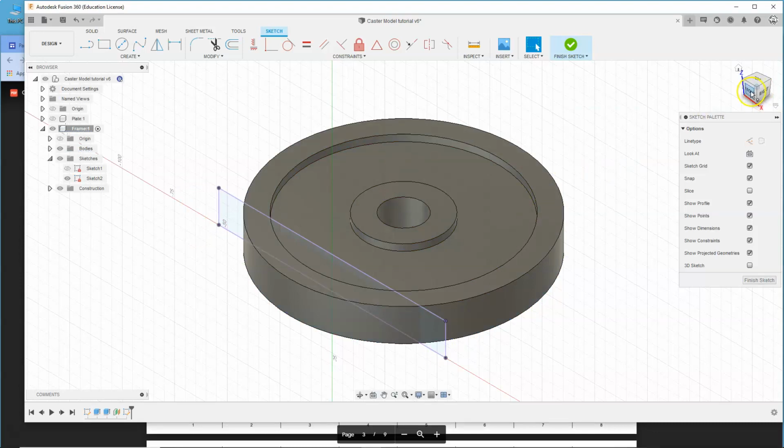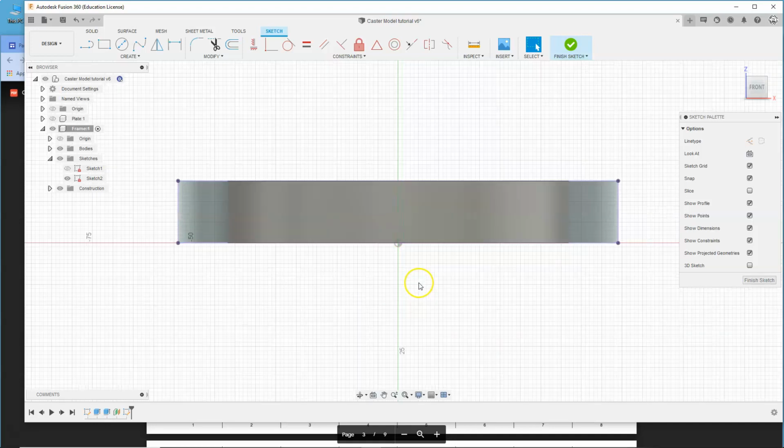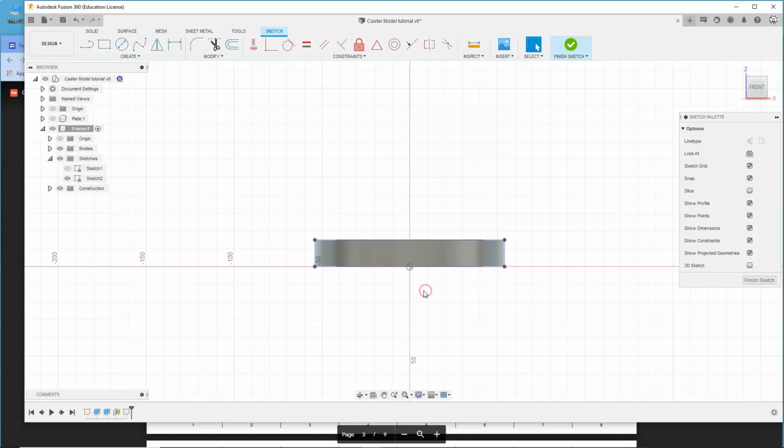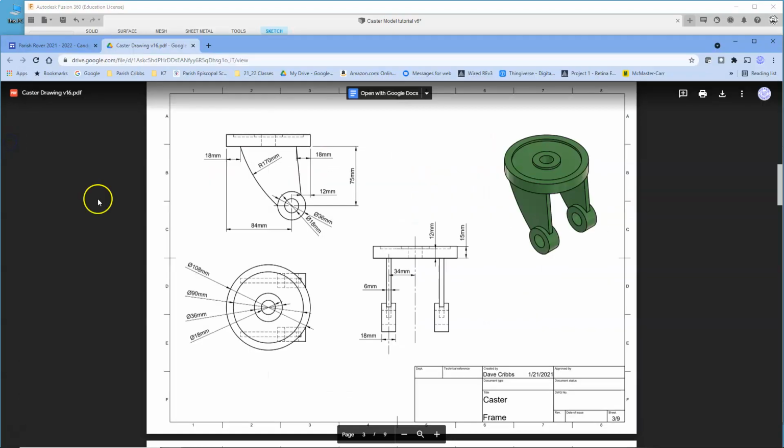I'm going to go back, look to the front face. This XZ plane is the plane I'm sketching on. So now I've got these purple lines and those dots at the corners. So that geometry is now in my sketch plane. So now I can use that to go ahead and make reference lines.